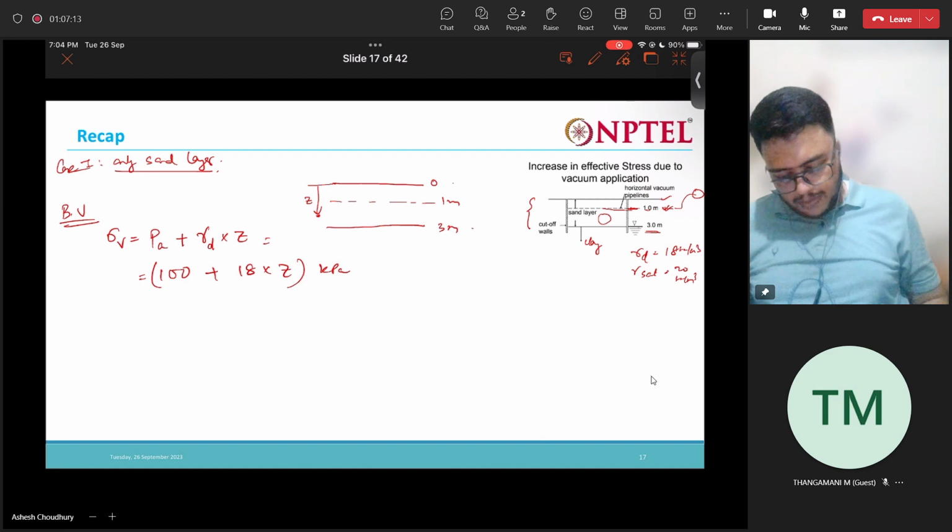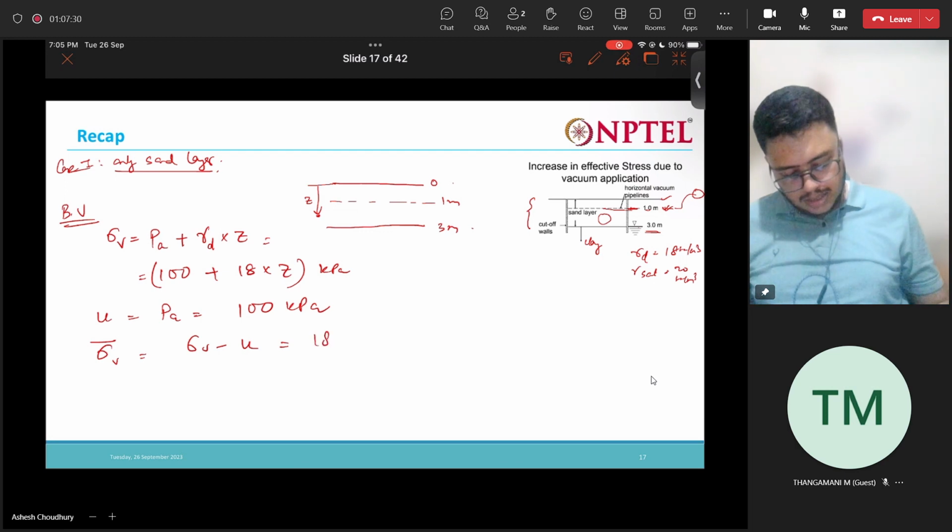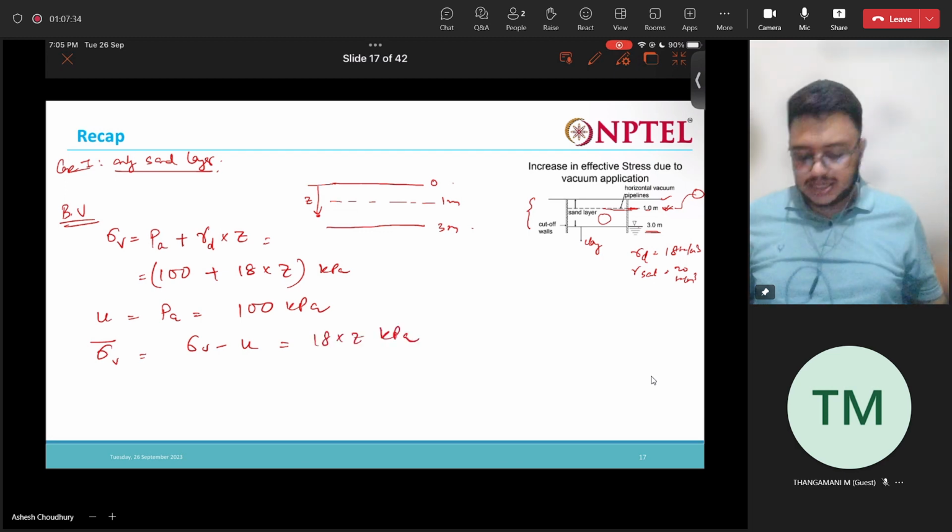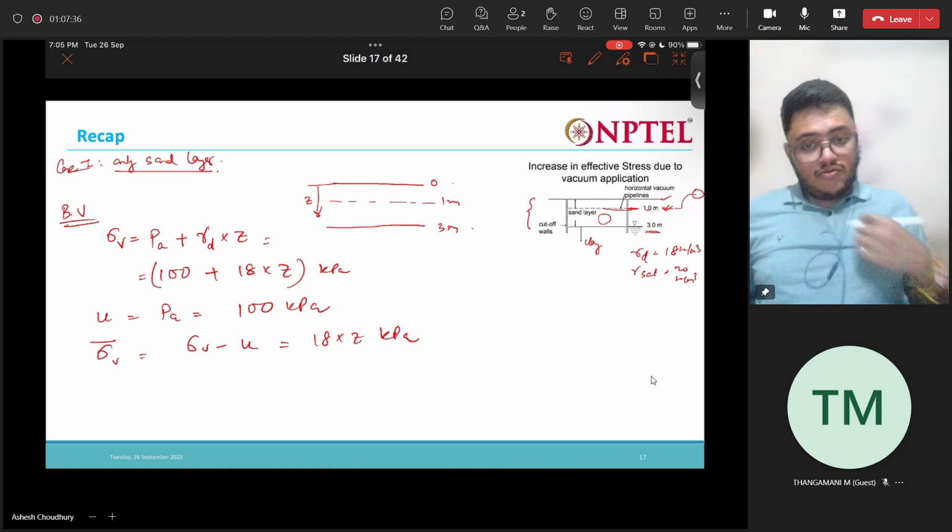What is the pore water pressure? Pore pressure is nothing but atmospheric pressure, Pa, 100, right? So what will be the effective stress? Total minus pore pressure. It is nothing but 18 into z. This is before the application of vacuum pressure.